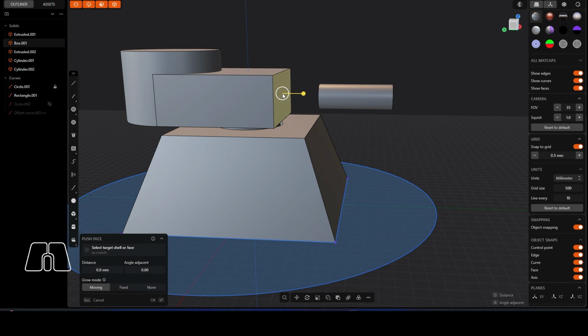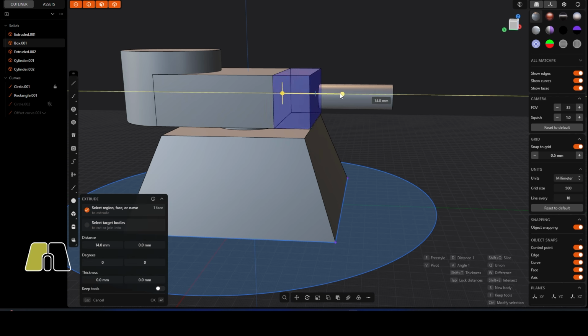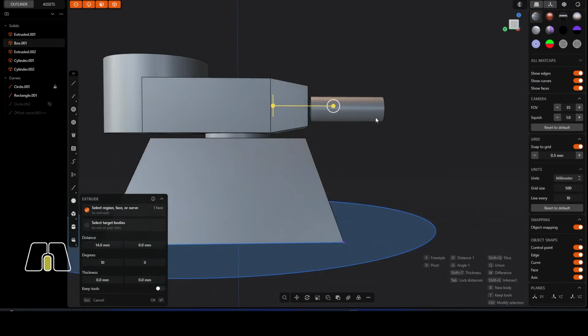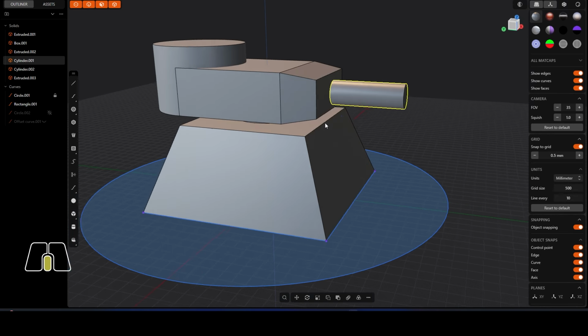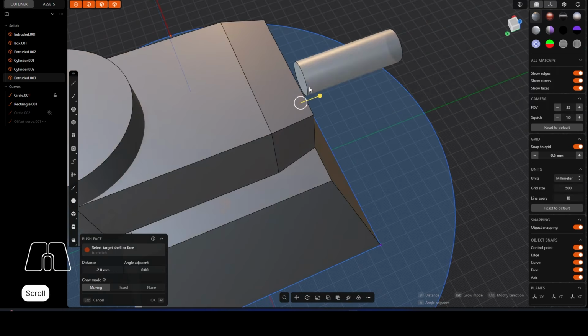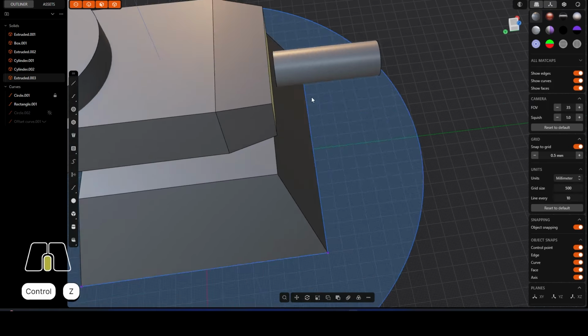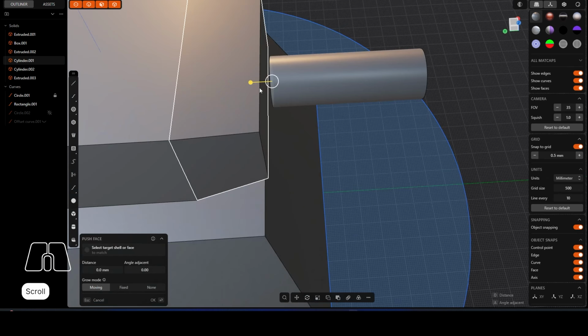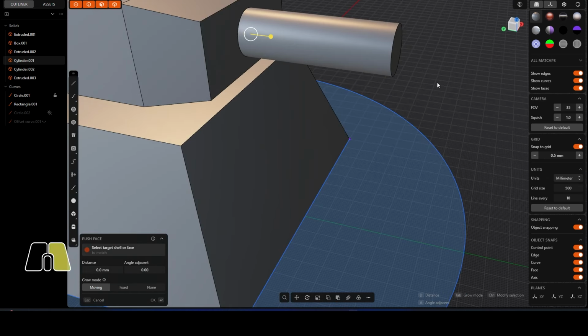And again, what we'll do is we'll use E to extrude. We're going to press B to do it as a new body. And then maybe we do about 5. Maybe we push it to about 10. Let's see. I think about 10 would be pretty good. And then we've got that nice transitional effect, and we can pull and push this and align it to this part here. Well, you should be able to anyway. So what we'll do is we'll align this bit to here, like so.